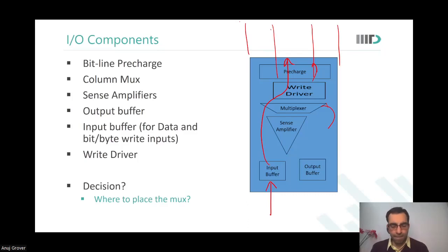So with the write driver, when I'm writing, for example, I'm taking the bit line to 0. I'm discharging the bit line to 0. So if I am placing it below the multiplexer, the additional RC delay that is coming will lead to it taking more time to bring that to 0. But before I start the word line on, I have already discharged that bit line, right? So how is writability improving? Even before I start the write, I have ensured that my bit line is discharged. Memory write time will not change.